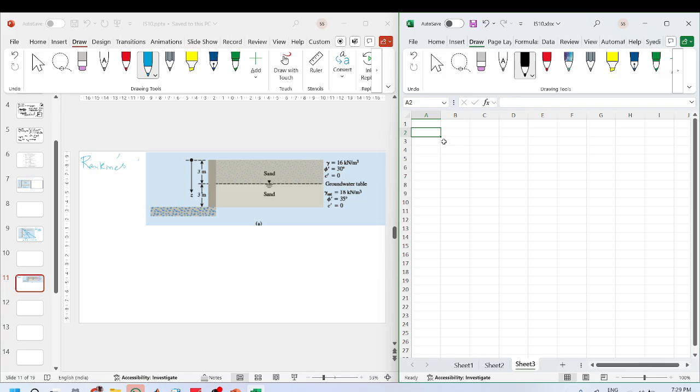Madam, before starting, can I raise a small question? Yes, please. When you're solving this example, what is our assumption in the wall? Do we have a weep hole or no weep hole? Because with weep holes there is no water pressure, but if weep holes are not there, then pressure will be there. What is our assumption? If there are weep holes, then there will not be any stagnation of water, isn't it?